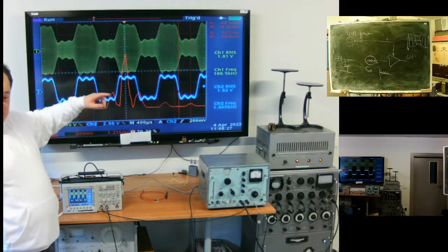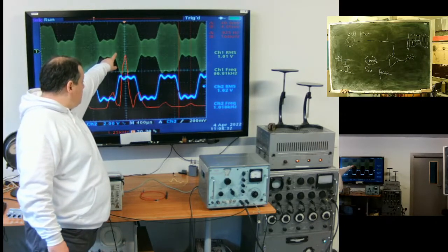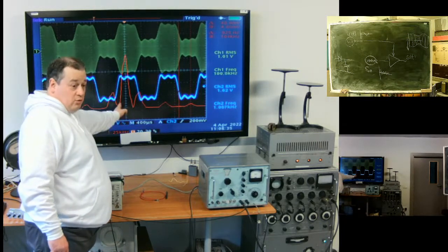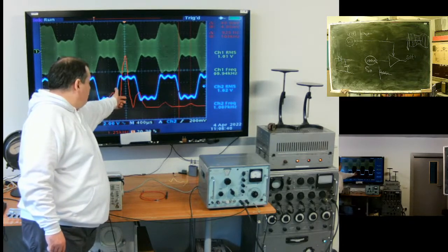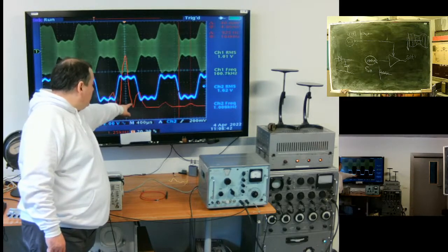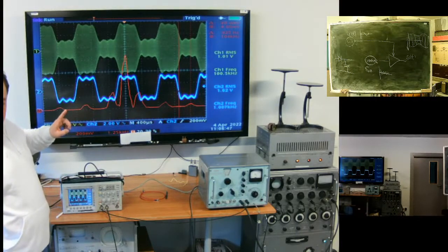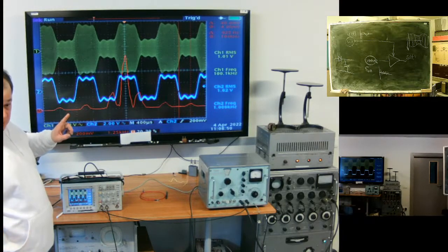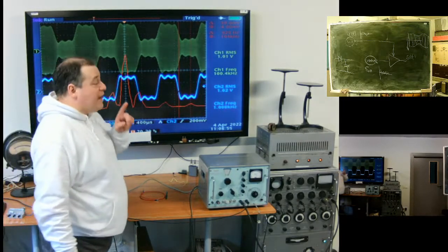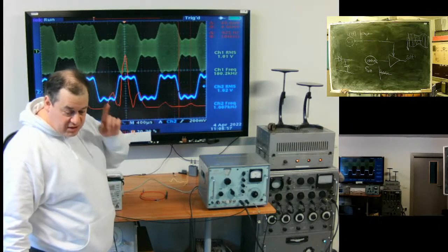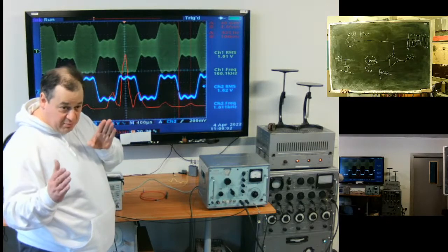We see how the spectrum of an amplitude modulated signal is formed. The central band, the carrier, is not carrying any information. In fact, this is useless. And the signal spreads symmetrically relative to the central frequency. See what's going on? In fact, we have the same information, say it's voice, transferred in two frequency bands.